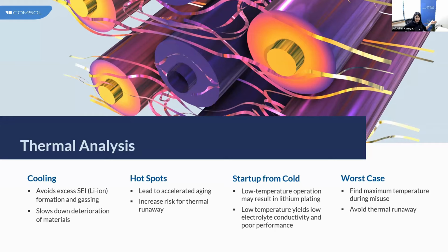You want to look at the entire battery pack and make sure that the temperature across the battery pack is uniform. You want to avoid having any hot spots, right? And then you get into the worst case scenario. Lithium ion batteries are known for this, and it is one of the issues that people are trying to address by moving to next generation batteries. But if temperature passes that threshold, then you have a big problem, because the cell might go under thermal runaway.